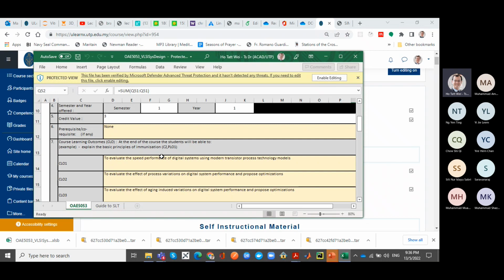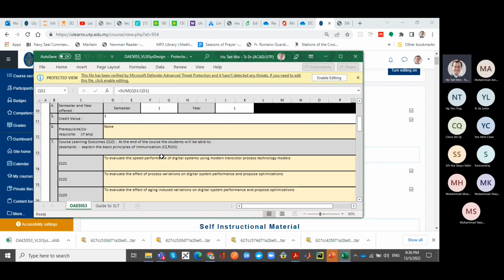Even the doping: at 7 nanometer, you're down to 2 or 3 dopant atoms per transistor. If you're missing one dopant atom, you're going to have a problem because the transistor parameters vary quite a bit. And because the dimensions are so small, the diffraction limit is on the order of 193 nanometer for UV, but now we are down to less than 10 nanometer sizes.